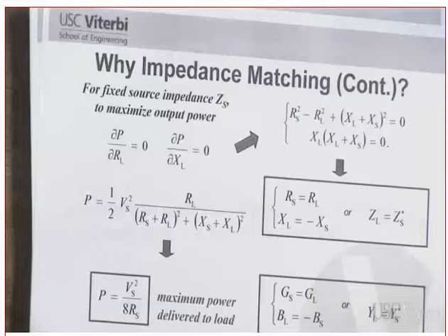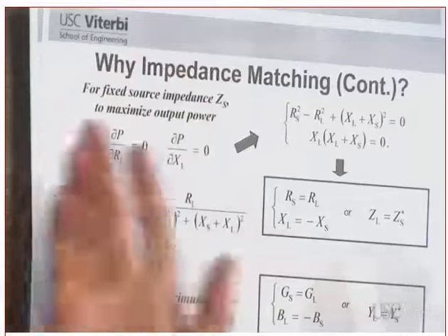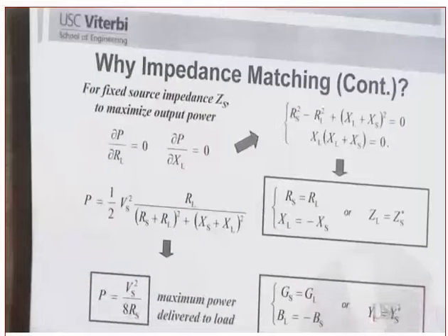Cannot hear you. Let me ask you a question. Is maximum power transfer and maximum voltage transfer the same thing? Yes or no? It's no. Why? For maximum voltage transfer, what should the load be? Open. Somebody said open. Hey, that's correct. It should be open, because if it is open, the voltage at the output is the same as the voltage of the source.